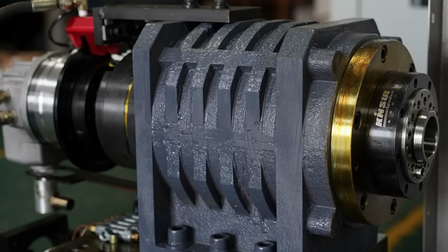Now, for the most modern CNC machines, that's super easy. They just turn the spindle itself into a huge motor. So it's got a big servo motor onto the main spindle, and they just drive that servo. There are also machines that have a big servo motor with a belt drive onto the spindle, but it's basically the same concept. The Schaublin 125 CNC, this was their generation 1 of doing a CNC conversion.